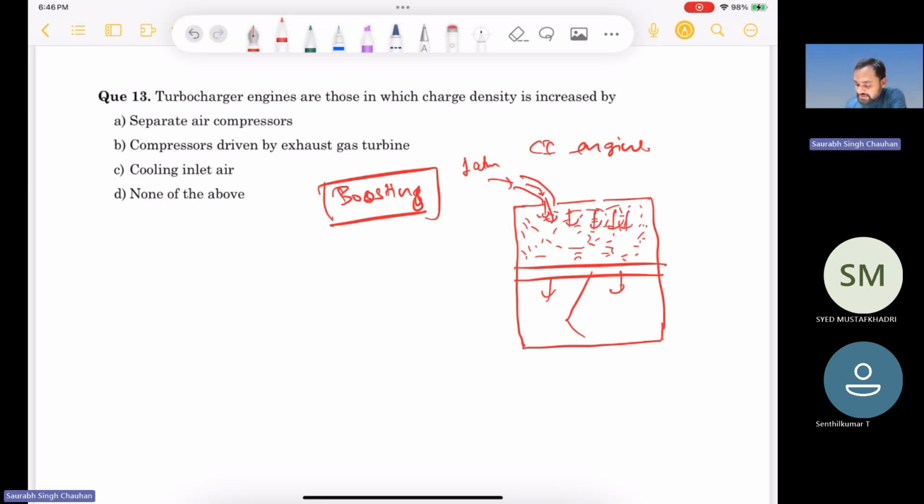Okay, and when the piston reaches the bottom dead center, the whole chamber will be filled with air. Then this air will be compressed. If sufficient time is available for filling the cylinder, then the pressure inside will be equal to 1 atmosphere. But in the real case, the pressure will be a little lower than atmospheric pressure, because volumetric efficiency cannot be more than 100% for naturally aspirated engines.